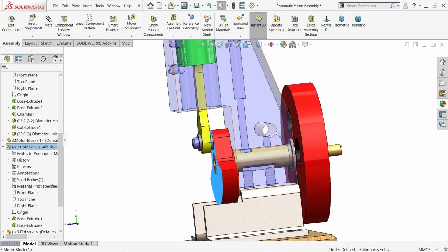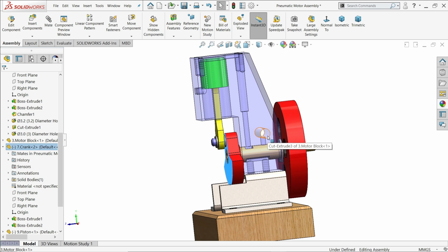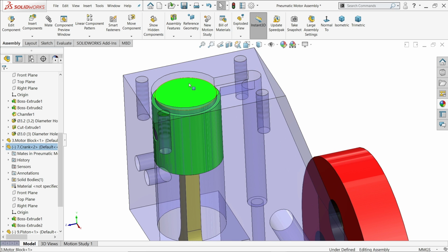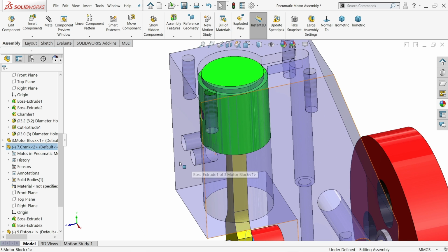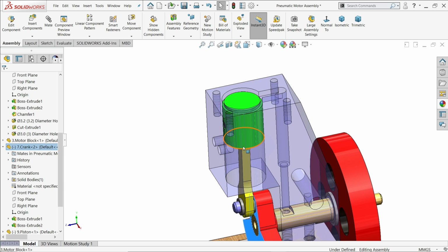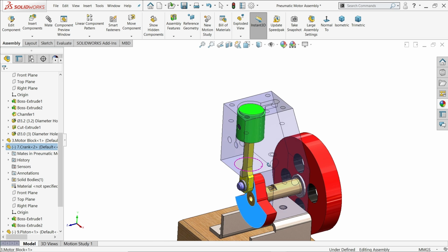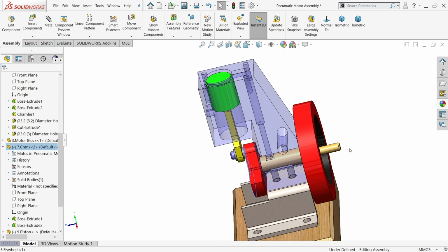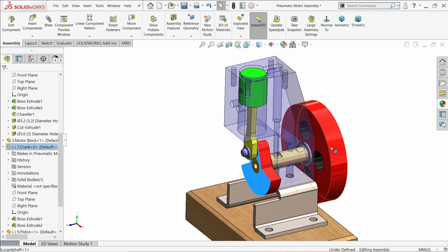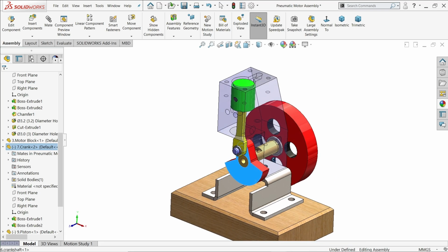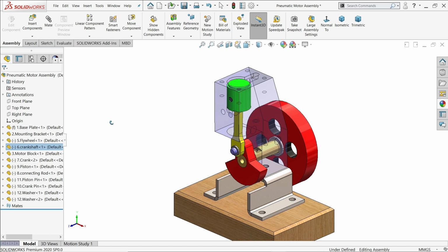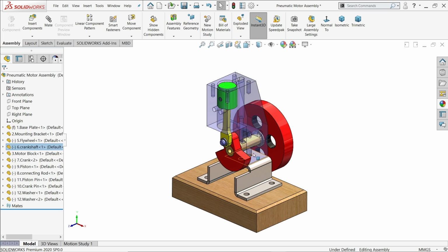So this is the main inlet for air. This air will pass through from here and come at the top and push this piston downward, and this is the exhaust hole. With the help of compressed air this engine is going to move, and the flywheel will help, and we can give a mechanical, rotational revolution to any mechanical part. It creates a small amount of torque, but it can.